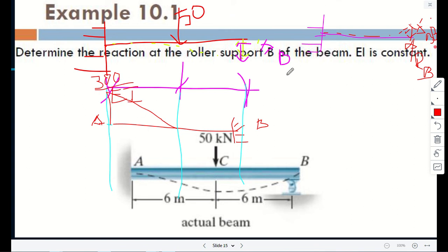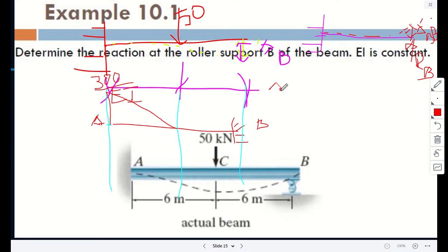On the conjugate beam, the fixed end becomes the free end, and the free end becomes the fixed end. Then you draw the moment, but you divide by EI. The moment of the M over EI diagram becomes the displacement, if you remember. I think it should have been covered in the previous course. Therefore, displacement at point B is the moment of the M over EI diagram.